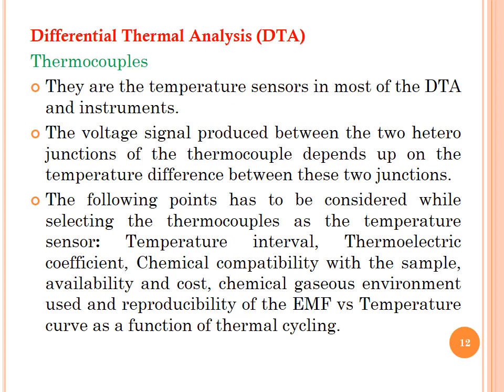The following points have to be considered while selecting the thermocouple as the temperature sensor: temperature interval, thermoelectric coefficient, chemical compatibility with the sample, availability and cost, chemical gaseous environment chosen, and reproducibility of the EMF versus temperature. EMF is the electromotive force, that is a driving force to drive the potential. EMF versus temperature curve as a function of thermal cycling.